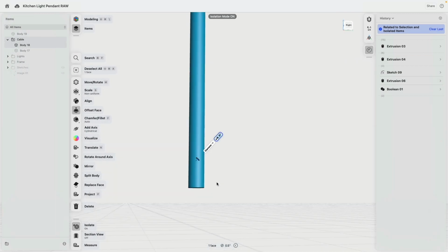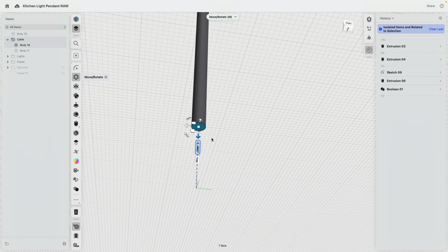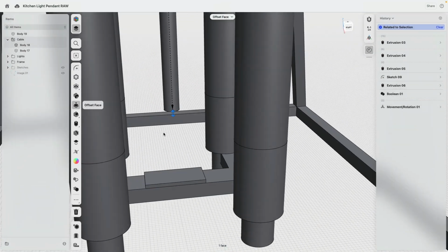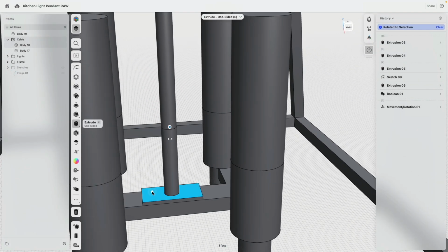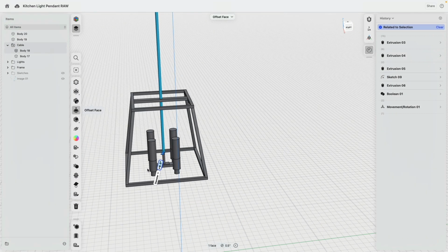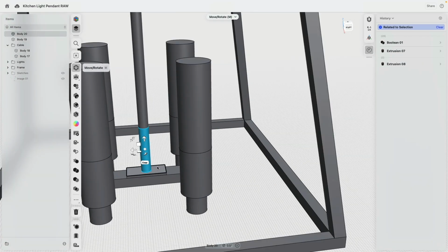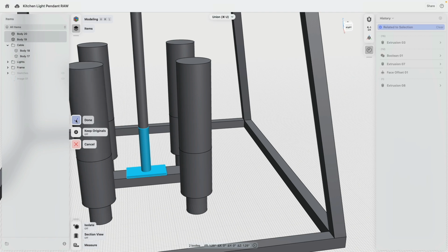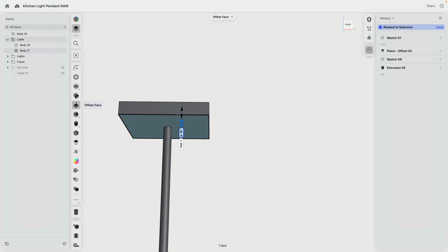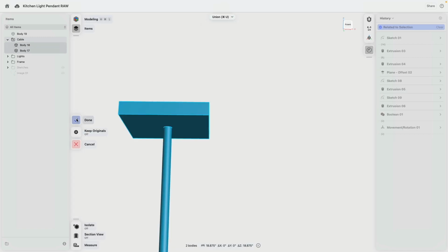This one here I would like to isolate, because what I'm going to do is this face I move up, let's say by 2.5 inches, unisolate, and then this I can extrude down onto this, but as a new body. Oh, look, looks like now there's something to screw into. This one and this one, for example, will be joined. That's going to be one piece. And these two, for example, let's say union.